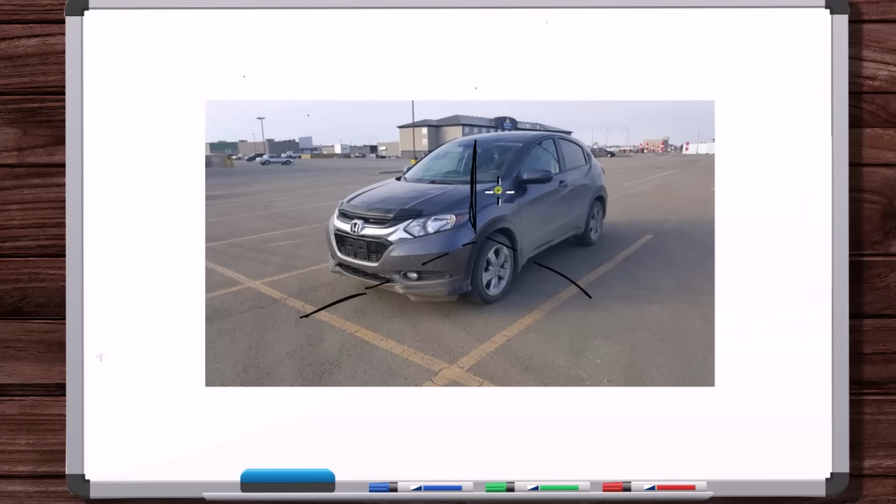That resultant force is going to be oriented in some random direction in 3D space, inside the plane, but some random direction. Now, you could put a coordinate system inside that plane and just specify that force in 2 dimensions, so you've reduced that entire force system to just 2 dimensions. But for a case like this, why would you do that? Because you want to see the forces relative to a coordinate system like this, the forward direction of the car. These coordinate directions make sense. You would want to represent that force with 3 components relative to these axes.